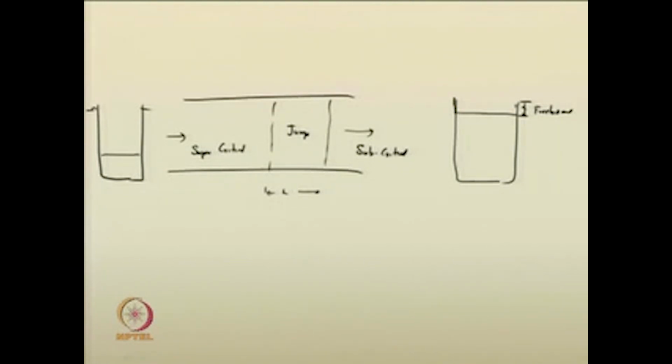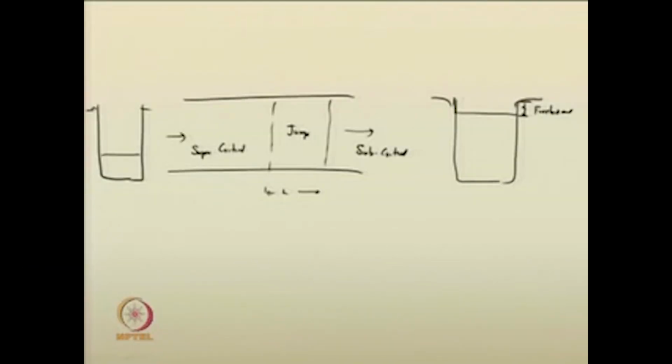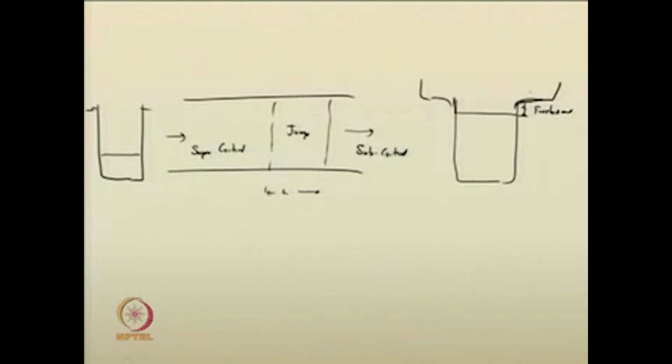For designing the freeboard, or also for designing the length, or to identify how much quantity of water may spill off in the plains. Some of the people provide freeboard in this aspect like this. Those also you need to take into account. So, for those cases you require the profile of the hydraulic jump.